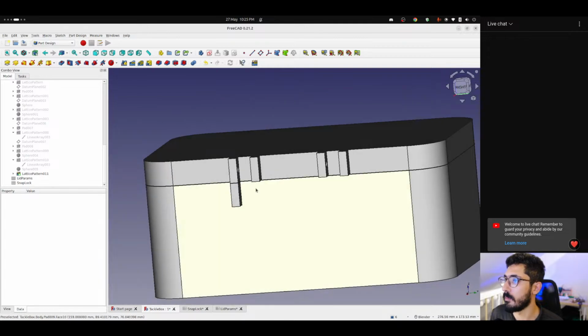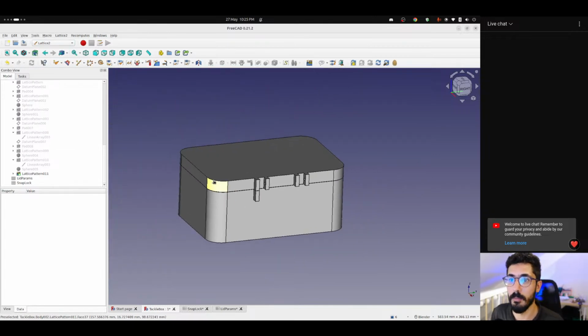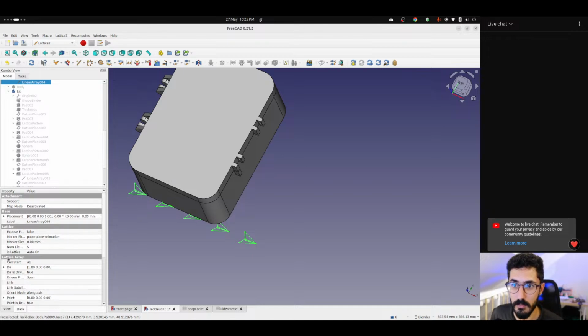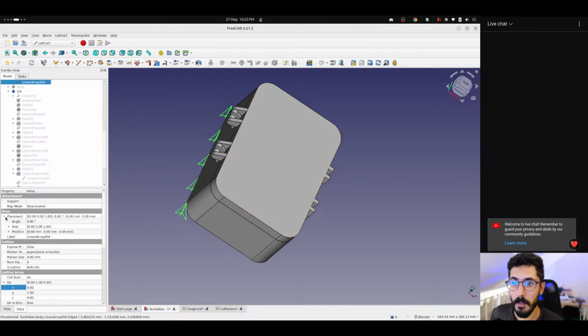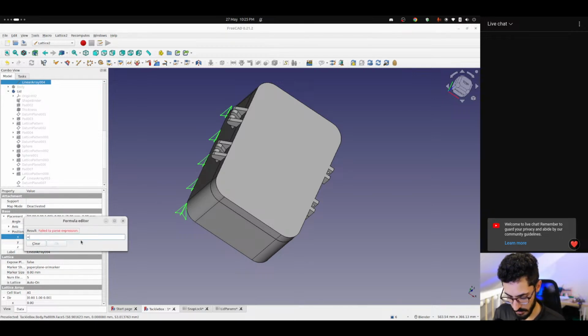And now we need to create basically the same array that we had at the top. So let's do that real quick. Lattice 2 workbench, create a new array. Direction 1 0. So we need it on the Y only, so just 1 on the Y. Placement position x-axis, so we need to go this way by tackle box dot total width.